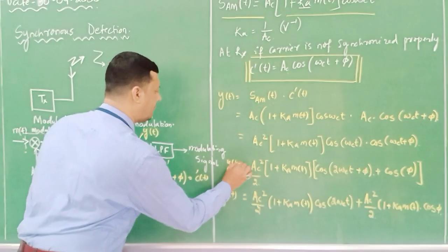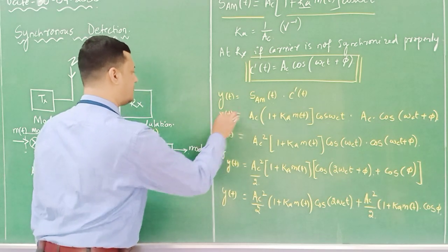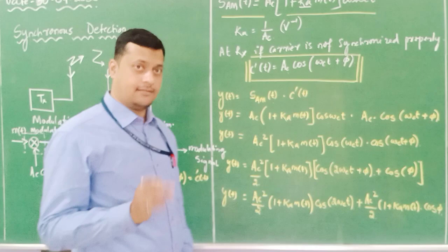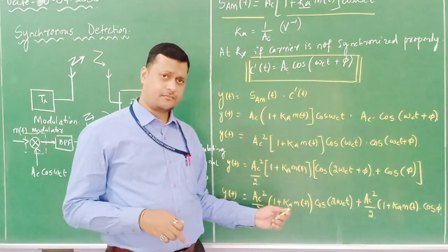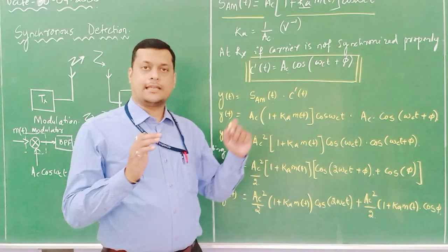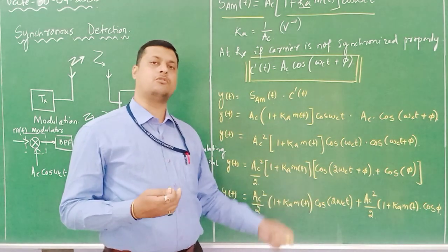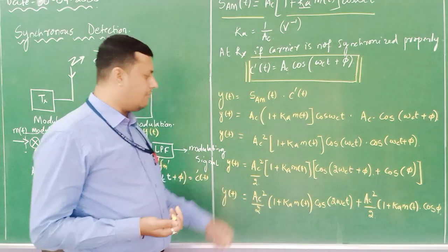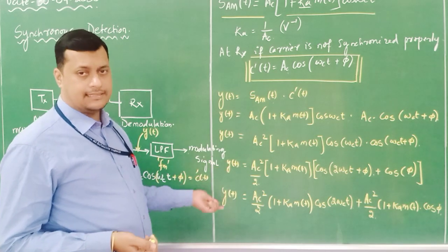Now this y(t) needs to be provided to the LPF so that it will suppress the DC component, the harmonic component, as well as the carrier frequency available at ωc or 2ωc. And what will be my output, that also we will discuss.